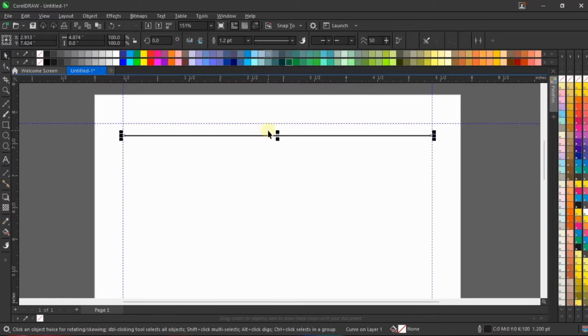To duplicate this line, click on the line, hold down your Control key so it will be on the same line. Click and hold, then drag down. Hold it, don't leave your Control key. Have you seen it showing you the size of the lines that you are about to duplicate? So if I leave this one now, whatever size I have for the first line or the first box is the same that will be duplicated. So right click immediately to duplicate.